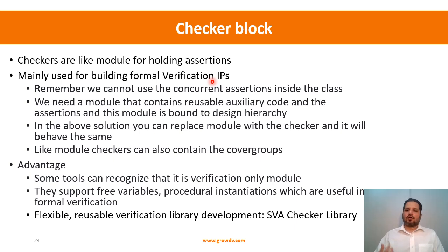Similarly, for the formal verification engine, assertion based verification IPs are created, and those are bundled using the checker construct. Remember that there are some limitations and some benefits of using checker blocks if you are building a formal verification IP. We cannot use concurrent assertions inside a class.